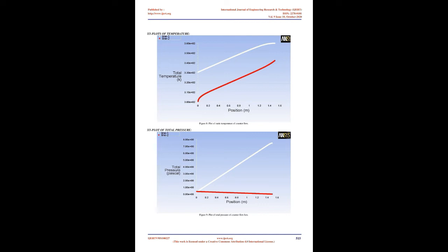4.1.1. Sketching. Out of the three planes, viz. XY plane, YZ plane and ZX plane, the XY plane is selected for the first sketch. A circle of diameter 70 mm and another circle with diameter 66 mm are drawn by selecting the circle in the sketching tab menu. Similarly, by selecting the XY plane again, we draw another sketch with two circles having diameters 42 mm and 34 mm.